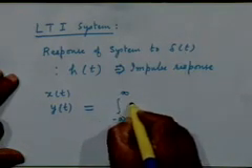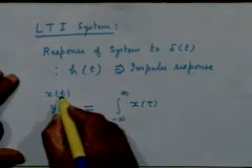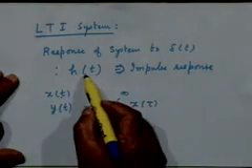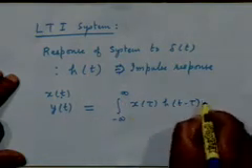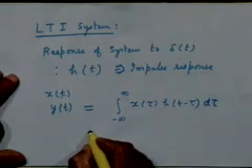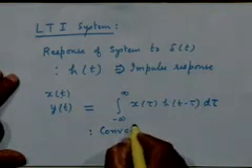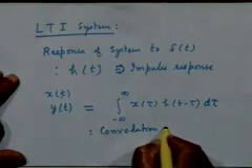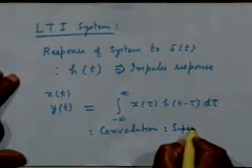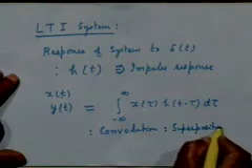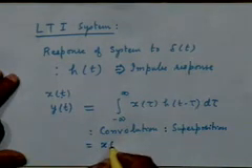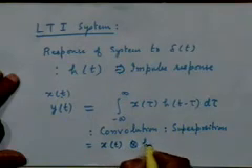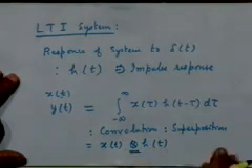That is, given the input x(t) and the impulse response h(t) of the system, the output can be expressed through this superposition formula, which is also called the convolution integral. It is a manifestation of the superposition property arising from the linearity of the system, and is usually expressed in the shorter notation x(t) convolved with h(t). This is the notation for the convolution operator.